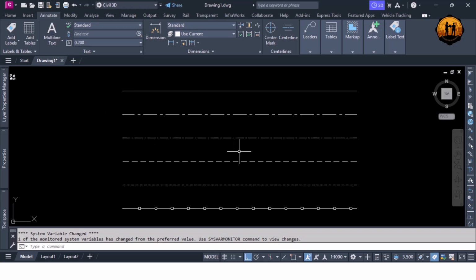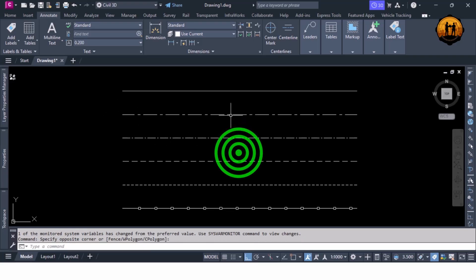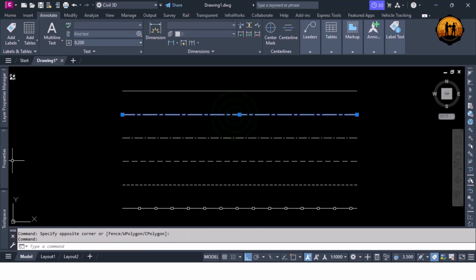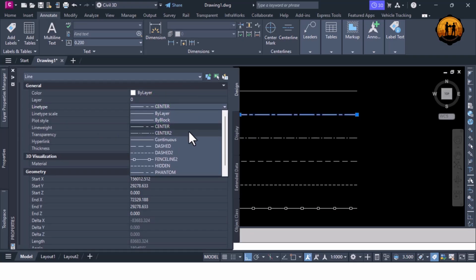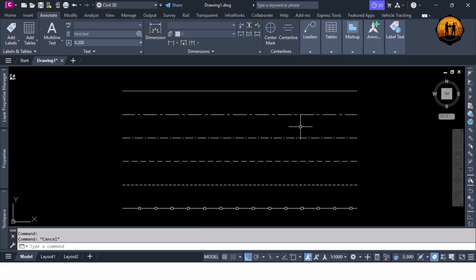You can choose which line type to use in the properties of the item or assign the line type to specific layers. This guide presents how to create custom line types in AutoCAD. To create a custom line type, one can either add the line type to the existing acad.lin file or use Express Tools. We will explore how to use either of the two options to create a custom line type.